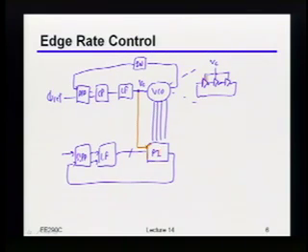So if my ring oscillator has a bunch of inverters in it, then I better also be using inverters inside of that thing. If my ring oscillator has some other random thing in it, then I should use whatever that other random thing is inside of my phase interpolator too. Because if I don't, then I don't know that I'm actually tracking the edge rates correctly. Does this make sense to people?